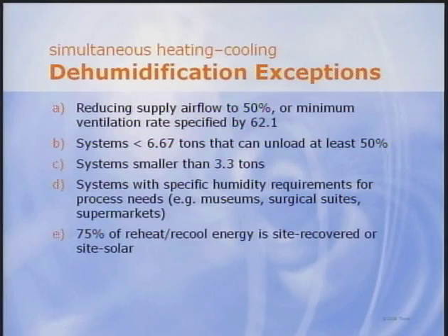Using exception E, reheat may be used at any time if 75% of that reheat energy is site recovered or site solar. We've seen many projects use this exception and recover heat, either directly from the refrigerant or from condenser water. For example, on a water-cooled chiller with a heat recovery condenser, it can help satisfy this exception. There's a broadcast and an engineer's newsletter on waterside energy recovery.